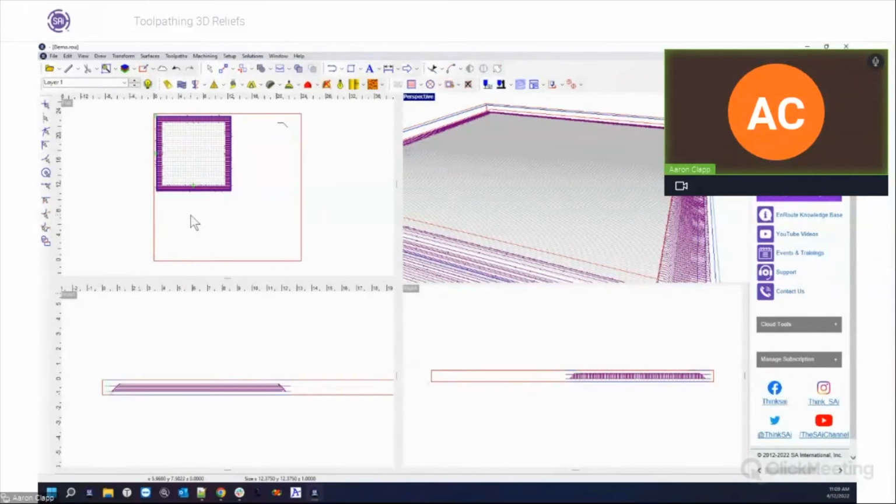Use the step rough if you need to create multiple passes or multiple tools, where you can rough out the material and then come back later with a smaller tool. Then lastly, use masks. If you can, and you don't need to cut a certain area, use a mask in order to filter out some of the nonsense that doesn't need to be cut and only cut the areas that are necessary. So using those masks is a key there as well. So hopefully that helps with 3D cutting.